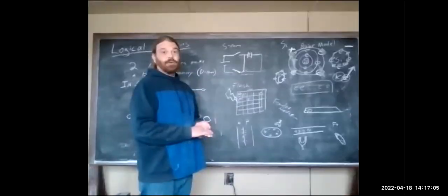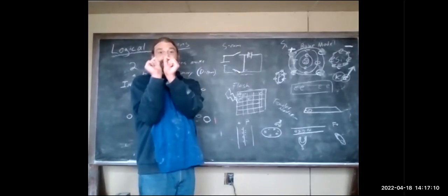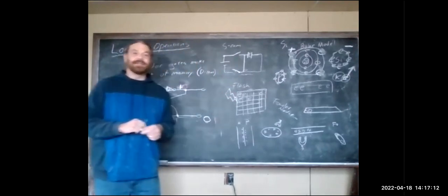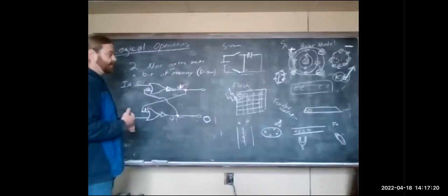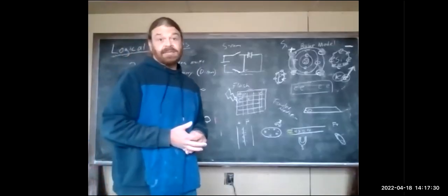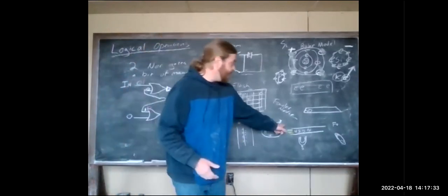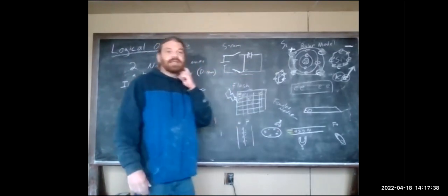That's really cool. And then it's organized, you know, it's a little bitty small thing. So with 8 tracks, we could put eight magnets next to each other on the width of that piece of tape. And that's why it's called an 8-track. 8 separate tracks on one piece of tape. Which also works really nice for computer code too, because then we can do 8 bits across instead of just 1 bit lengthwise on the tape.